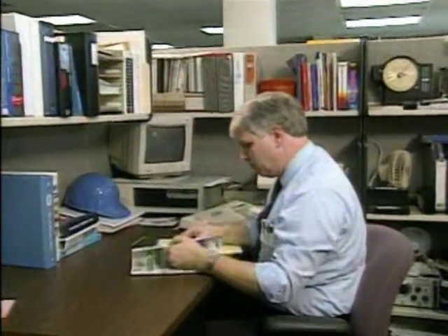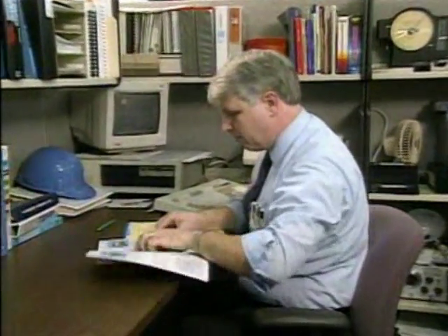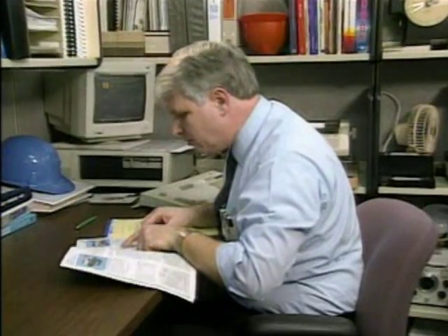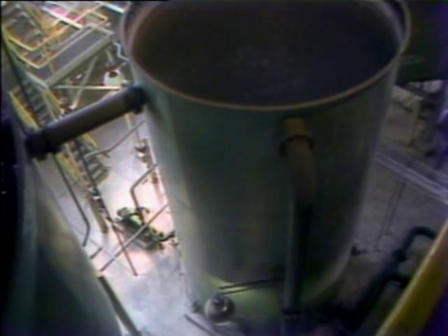Another factor that is often examined when looking at the operation of pumps is head. Head is basically a measurement of pressure. It's the pressure caused by the weight of a column of liquid as a result of its height. Head measurements are usually given in feet.